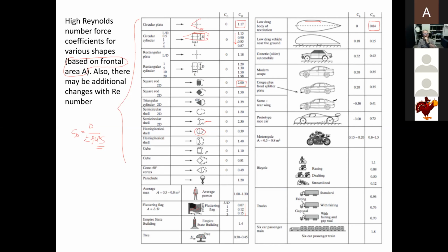Now, in this case, on the left-hand side, I did put the lift coefficient. The lift coefficient is defined exactly as the drag, but the drag acts parallel to the free stream, while the lift acts normal to the free stream. All cases here on the left-hand side are symmetric. Therefore, we don't expect, there may be momentary side forces because of flow separation, but we don't expect any side forces or whatever we call lift.